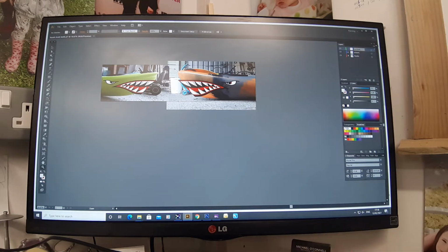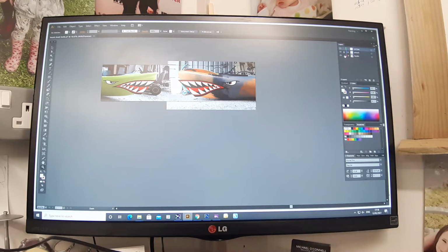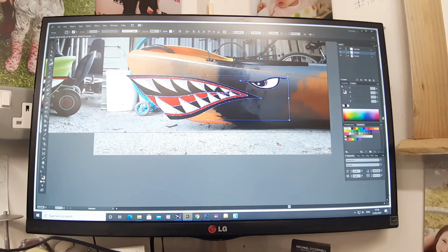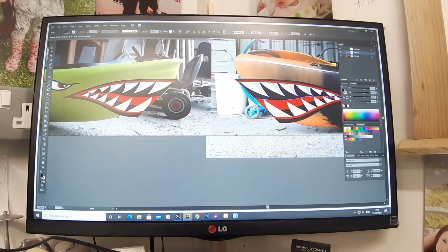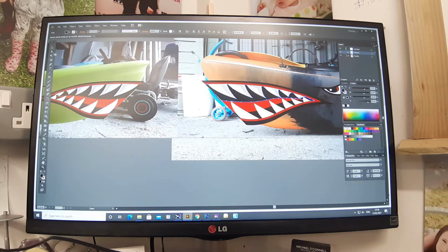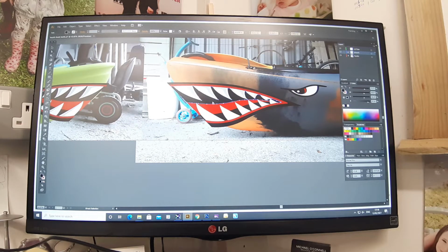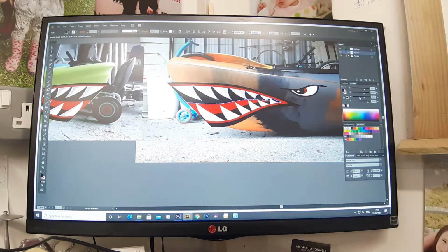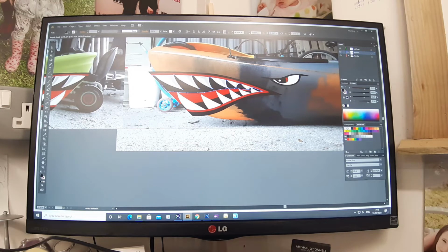I just like to have that whole complete layer of cut lines as a separate layer. So what I'm going to do is, sometimes a color that looks like black may not give you the value of black. So when I go to the direct select tool over here on the top left hand side, the arrow, when I select the black color here, it's not in fact black, because if you look over here on the right, you'll see the value for that is cyan 72, magenta 68, yellow 66, black is 87. So it's not a true black, it's going to be a dirty kind of a browny black.